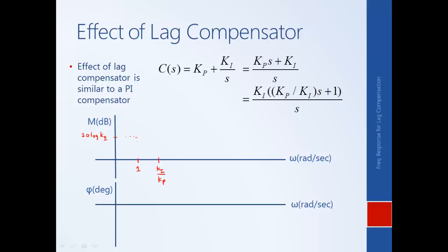And so at those lower frequencies, the slope will be entirely due to the integrator. And then when the zero enters in, the slope will flatten out because the integrator has a slope of minus 20, the zero has a slope of plus 20 dBs per decade. You add them together, that adds up to 0.